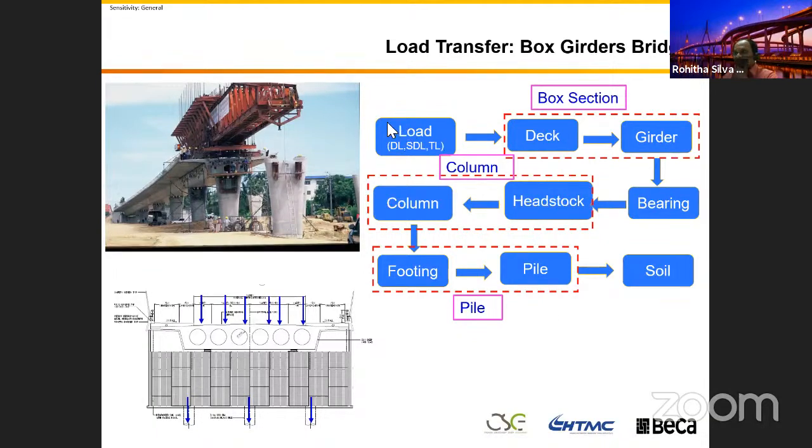The reason is the load transfer mechanism. The box, like we saw here, carries all the load and sends it straight to the column through the bearing, then to the pile. Especially for these bridges, Bangkok is clay, so we use the flexibility of the ground. One thing I forgot to mention before, you have to be very friendly with your geotechnical friends. You need their support and their input when you are making these decisions.